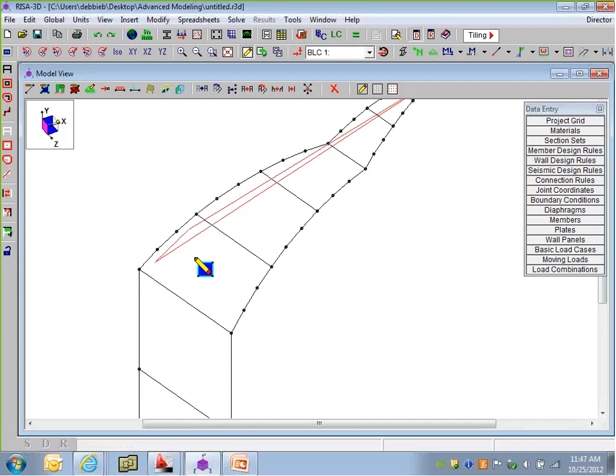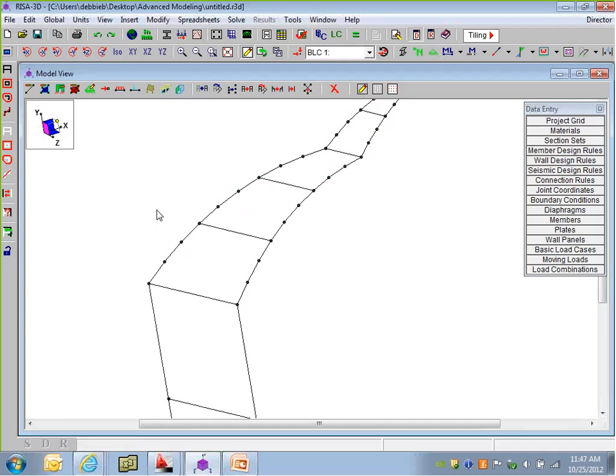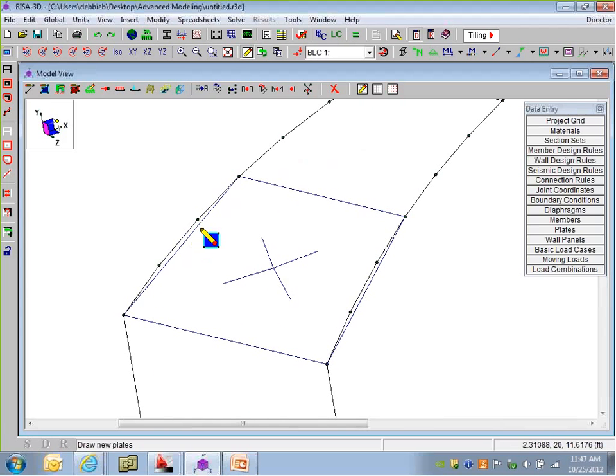It's actually, I'm changing slope. So if I started to do just a massive plate like this, you can see just from that red line, and this is kind of a good example, it won't really work. This isn't connecting to that point. So it's just math, right? As you draw this line to this point, it misses the slope. So what you're really going to want to do is draw all the way around each point.